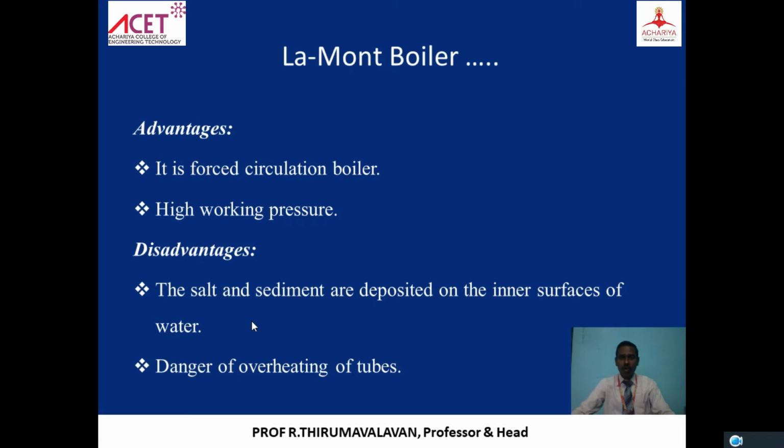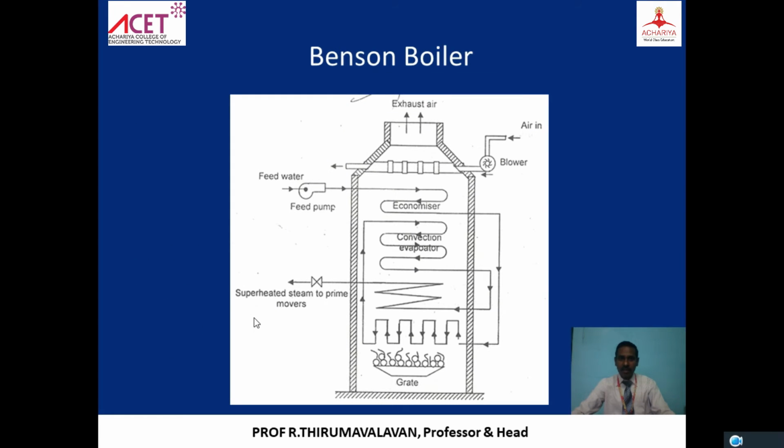These difficulties may be overcome by another boiler, the Benson boiler. The difference between the Benson boiler and the Lamont boiler is that the Benson boiler does not have a separate boiler drum. The Lamont boiler has a separate drum, from which the steam is separated. But instead of a drum, here they use two types of heaters.